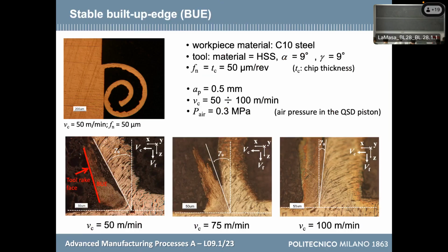Now, another phenomenon that is well known in milling is the built-up edge, which is a behavior that is represented in this micrography. We obtained this micrography in our laboratory with a special equipment. Because, you know, for obtaining this, you have somehow to freeze the cutting action, which is not easy. In order to freeze it, what we did at that time was building a system for quickly removing the tool from the workpiece. And for doing that, there was a piston loaded with compressed air. And so we triggered the piston in order to release the energy and in order to let the tool rotate.